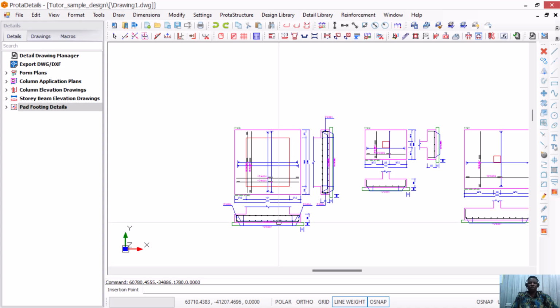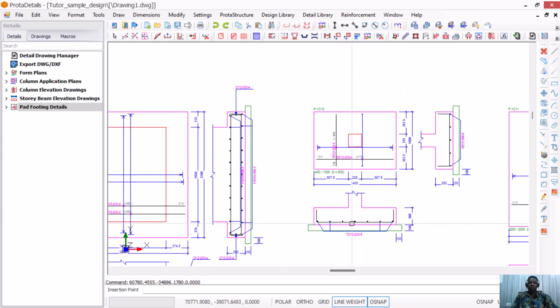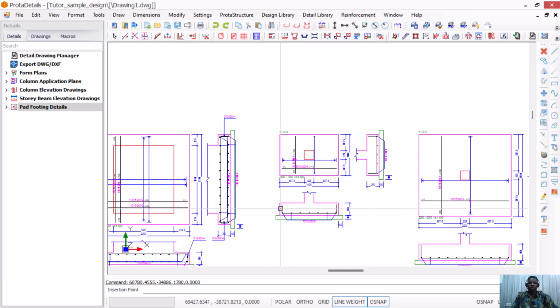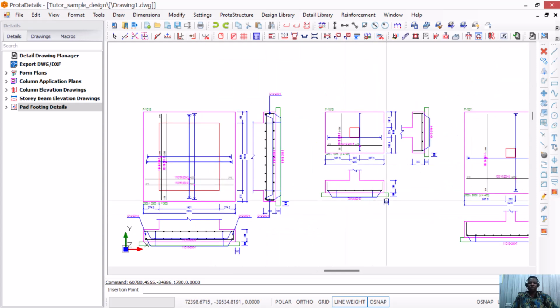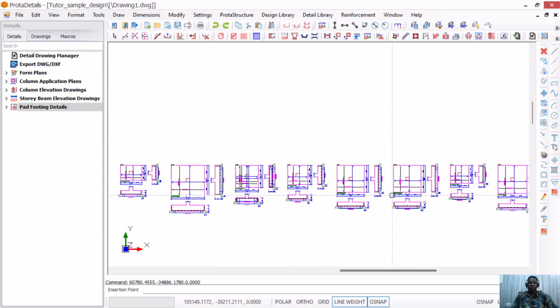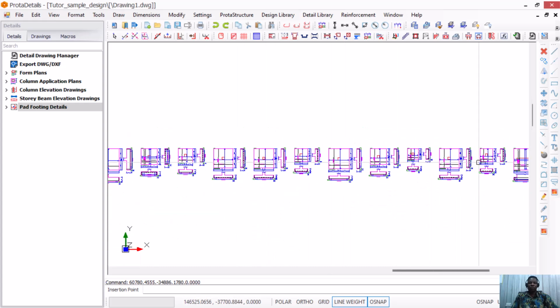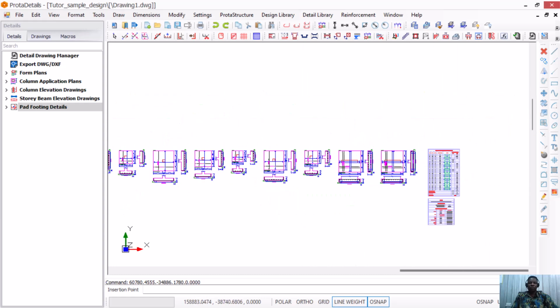You can see from our design where we have the double, where we have the multiple columns. In the multiple column, you're going to see we have top and bottom reinforcement, and where we have a single, we designed it with a single reinforcement. That's why you see it at the bottom. And for the double, we have top and bottom reinforcement, different from this. So all the areas where we have double column have top and bottom reinforcement. Don't get confused, we have top and bottom for it. That's why we see this.